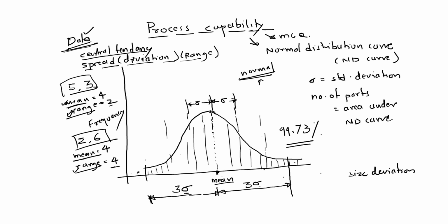The manufacturing process with which the shafts are manufactured, and then we have put the data here, various numbers we have put, and we got the frequencies of each number, each size. This everything happened considering the process with which those shafts are manufactured has no error. This process is normal. This is the assumption actually. And then we are defining these limits, and most of the shafts will be falling in this limit, and those shafts will be 99.73%. This is a pre-discussion about the process capability.